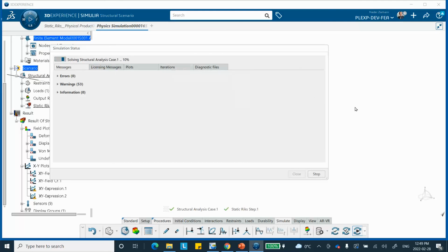I think in my fixed step, I changed it to 0.1. If you change it to something bigger, you may get a jagged curve, but that's something you can try. I think I changed my increment in the fixed step from 1 to 0.1, if I'm not mistaken.